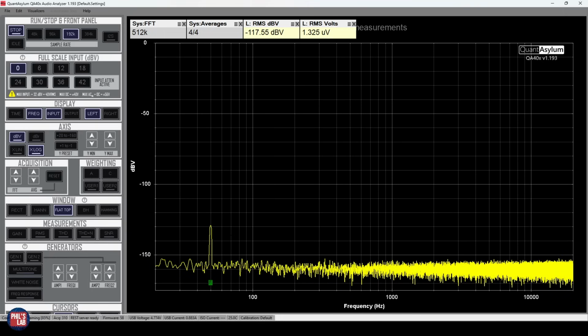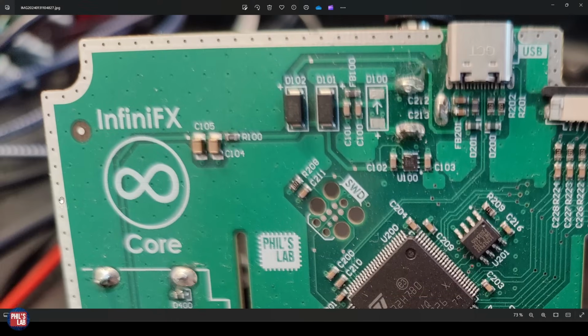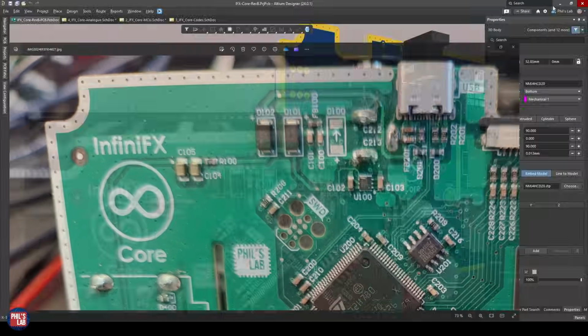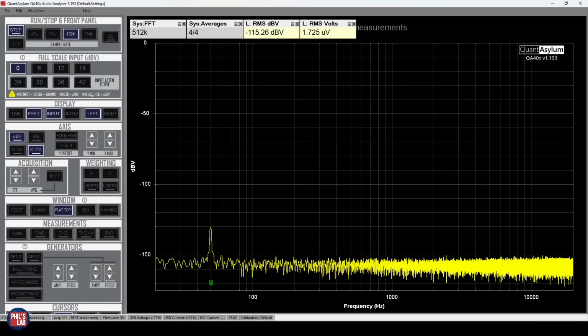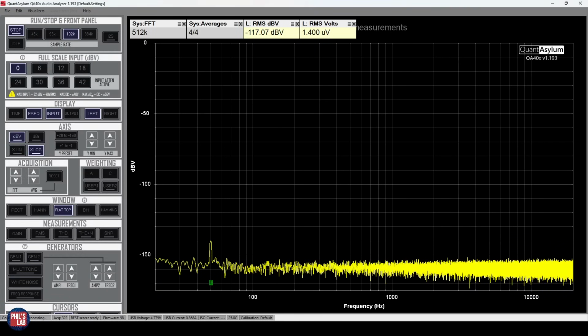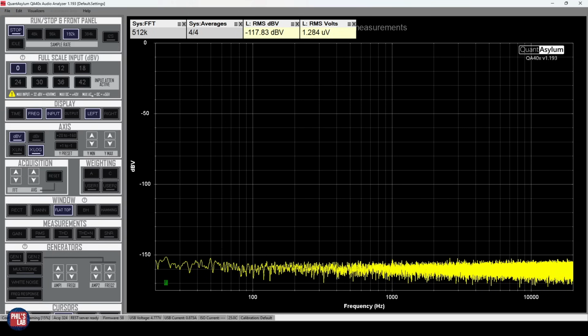The way to fix that is, for example, tie your system to a common ground point. So, for example, I could now take a USB connector where the shield is typically grounded and then touch that to the strip I have on the outside of my board, which is grounded on my PCB, which effectively is connected to mains ground as well, ultimately. So if I do that, we can see this mains spike is now dropping because we now have to find a common reference between all of our systems. And this is how we can then eliminate this measurement error, which is this feed-through of the mains 50 Hz frequency in our case.